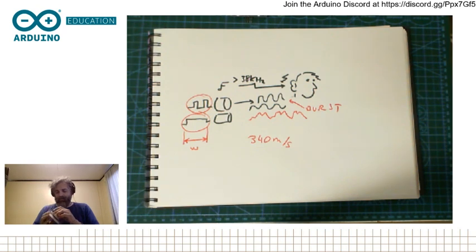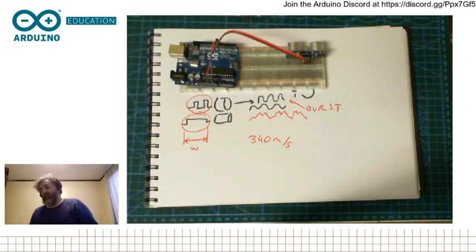Okay, we just make sure. And then I plug it to Arduino, ground, 5 volts. And then the signal is actually a digital signal, and this is very important. People don't understand this, but we are not dealing here with an analog signal, not with a ping sensor. We're dealing with a digital signal.